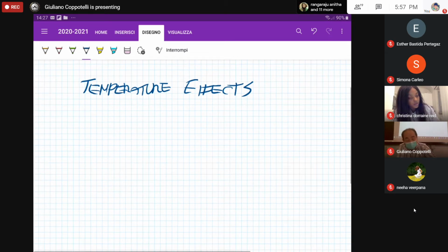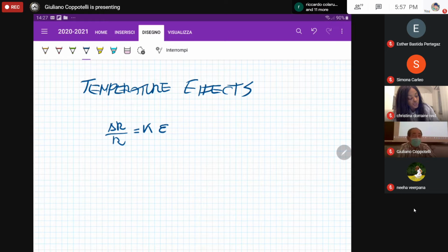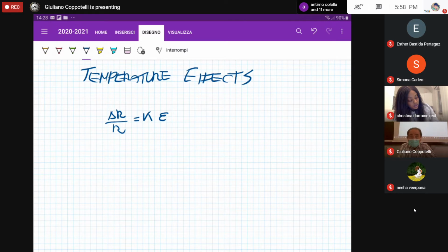And that equation is that the relative change of the resistance is due to the strain, just by following that equation, in which K, once again, is the strain gauge factor. It could be global or just strain gauge, according to whether or not we are considering the transfer sensitivity effect. K is the gauge factor. Typical value is 2.